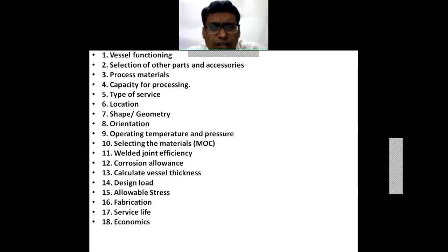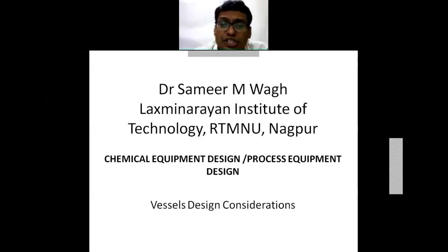But generally 20 to 50 years of service life is considered, because of innovations and new products, and the outdating of products that may arise if it is for a very long service life. And finally, the economic aspects have to be studied. So all these are my vessel design considerations.